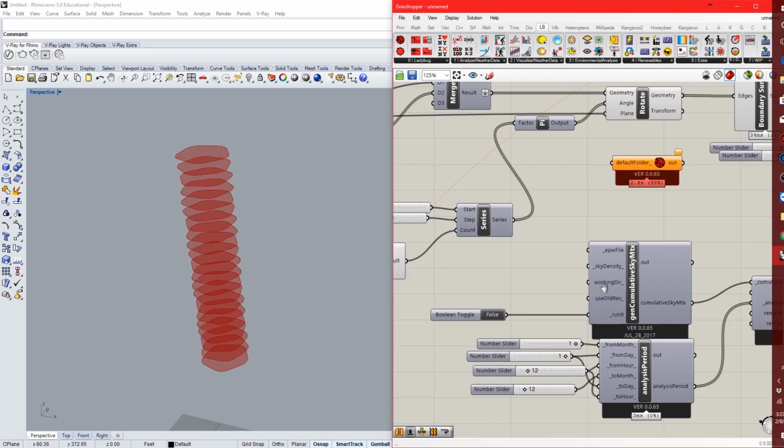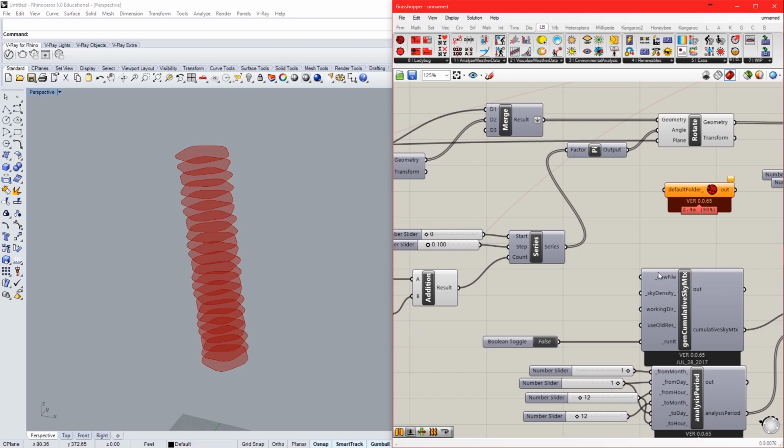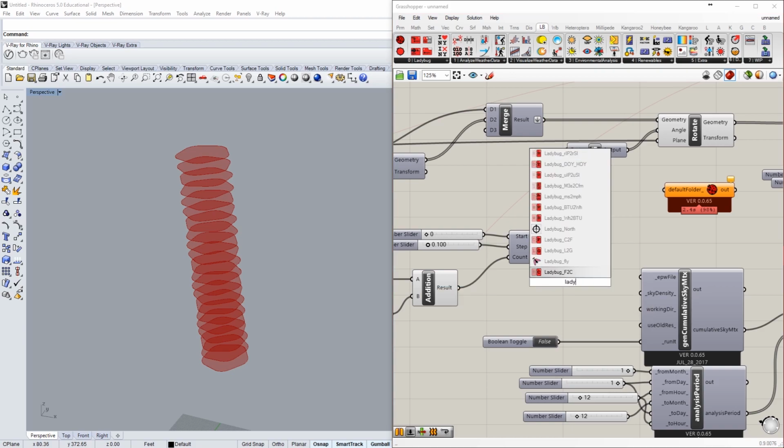Go back to Rhino or Grasshopper. Okay, EPW weather file. I hover over it, the output of the Ladybug open EPW component, right? So there's a Ladybug component to open that file. So I search Ladybug open EPW weather file, right? You hover over anything in Grasshopper and it's going to give you clues as to what you need, right? Even if you don't understand how it works, even if you search the YouTube videos and you don't understand, there's a way to move around in here where you can deduce it yourself, right?